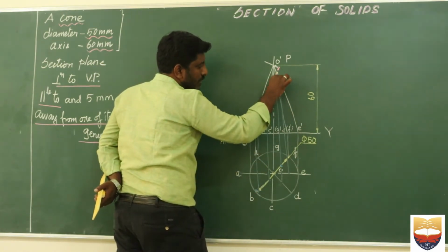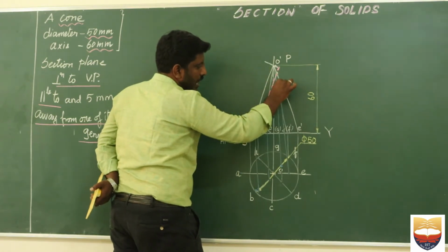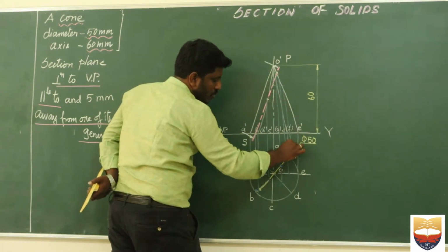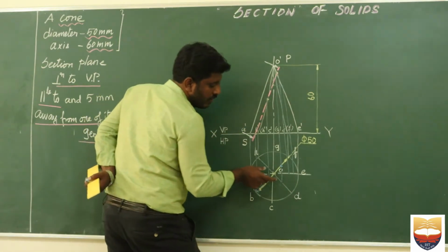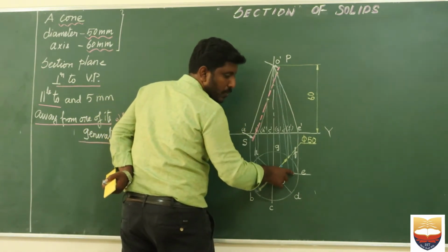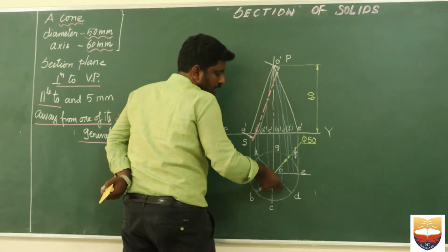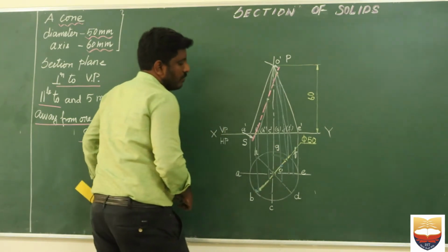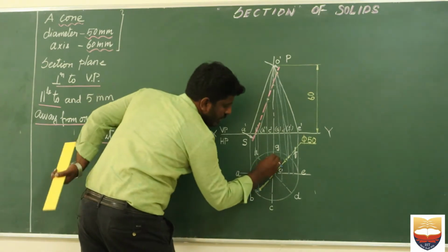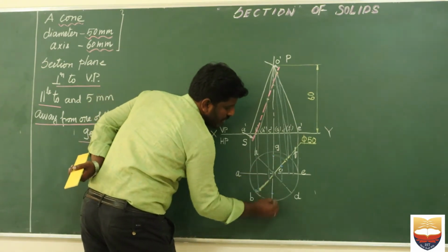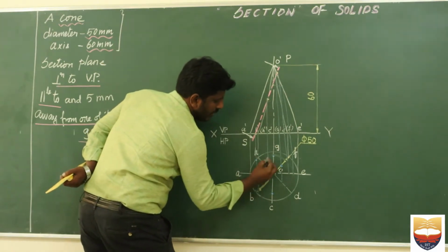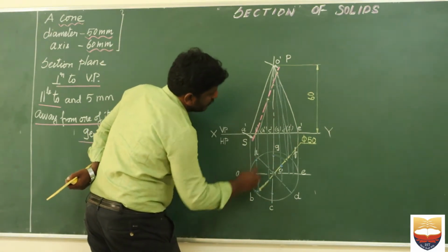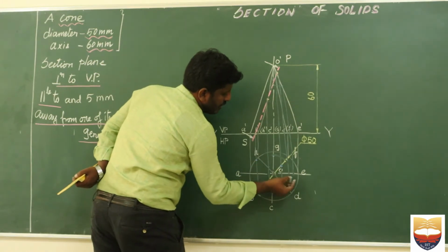Okay. So from where this is E dash to O dash, I am bringing this point to E dash to O dash. Now I use my compass. I will take my compass with the O as a center, the projected point as a radius. I cut an arc here and I cut an arc at the top. So I will be having a point over here and I will be having a point over here. See, I am having a point here and approximately I am having a point here. I am having a point here and then I am having a point here.